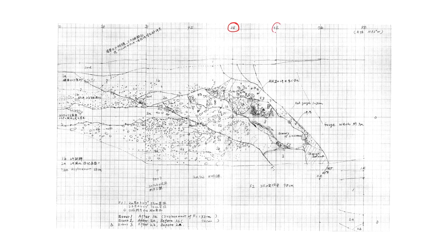If you see here, if you start from here, probably this is 1 and this is 2, and the numbering which has been given is 1E, 2E, and it goes up to 8E. Now E represents the east wall, the east facing wall. Similarly, you have to also look at the west wall. If your trench is oriented north-south, then you will have east and west walls exposed. So that is the coding which has been done, and coding for each vertical grid line has to be done.